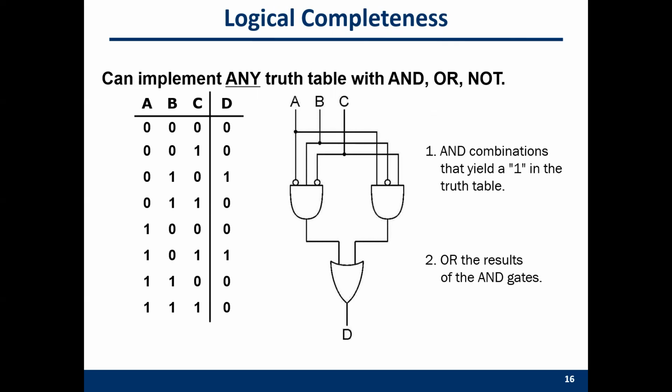So by AND, OR, and NOT gates, we can always implement any truth table here. The truth table can define a function. By 3 types of gates, we can implement all functions. First, we just need to pick up the rows which can generate a 1 output.